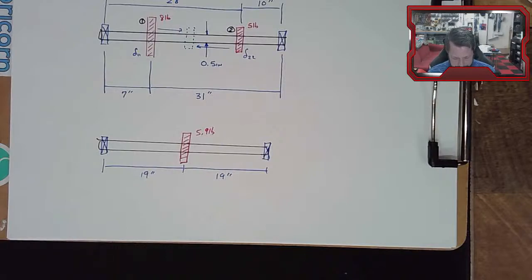So it says 67 radians per second. That's the combination of the elements at 72 and the shaft at 174. When you combine them, you get 67-ish radians per second. The combination should be lower, kind of like springs in series, than either individual one.